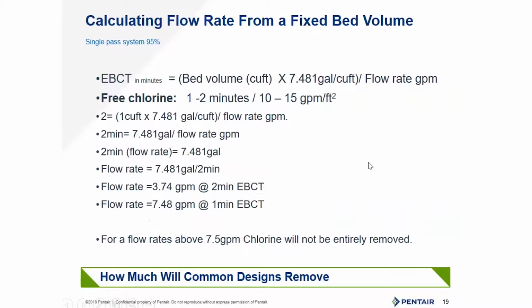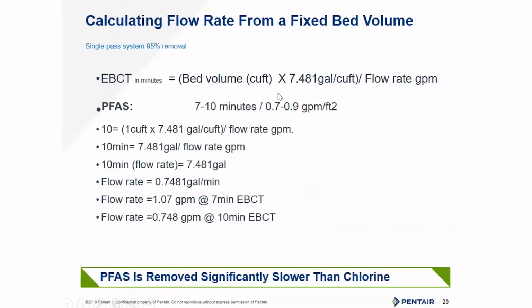This is one way to look at it. If you wanted to say that same bed, well, we know how much chlorine we're going to remove, that's no problem. Well, what about PFAS? Well, I'll get rid of all the PFAS at a 7 minute empty bed contact time if I'm flowing only a gallon per minute.